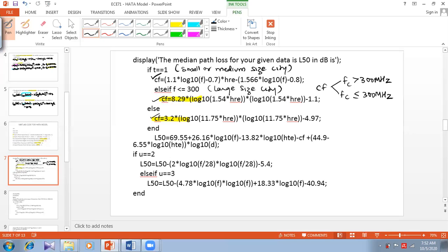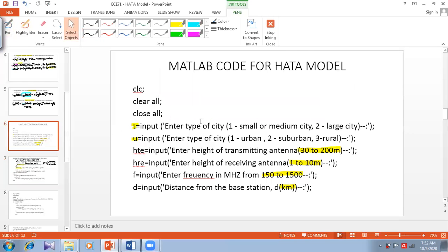So the first step of calculation is over. Now we have calculated the urban path loss, that is path loss for an urban area using the Hata model. Now as we had discussed earlier, again there are two considerations. It can be a suburban area or a rural area. So depending on that, you will again have to compute, correct? So we have taken a consideration as u here now. U, if it is a suburban area.